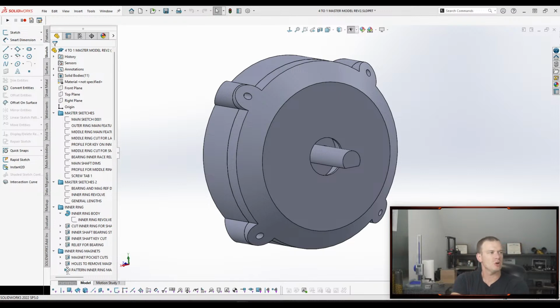Yes, you can protect your part when working with others by using the derived technique. Derived is very similar to your master model, right? The master model level, if you think of it as the same as that folder level part where we're putting all our sketches that we eventually derive, you can't edit a derived sketch. So you have to go into that folder level in order to make any changes. And so that's what you can distribute amongst engineers and have them design independently.